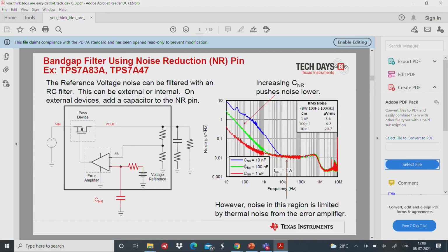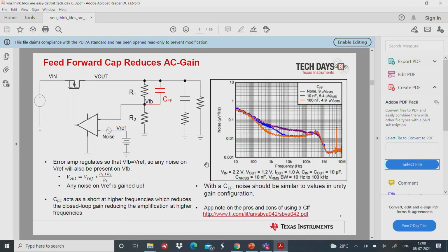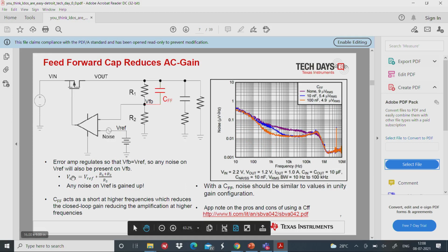This picture is also well known to you now, that this is the series pass of an LDO and this is the error amplifier, these are the sensing resistors and so on, and you can see that the V out is nothing but Vref multiplied by this term, which involves the 2 sensing resistors, and that is what your V out is usually held at.